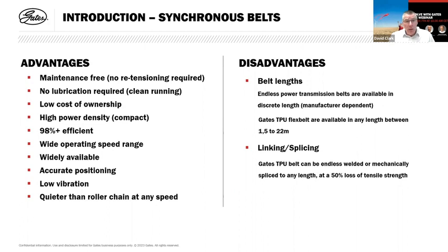Gates belts offer accurate positioning. Synchronous belt teeth mesh closely with pulley grooves, and that allows you to minimize backlash and increase the accuracy of your positioning. They are low vibration.